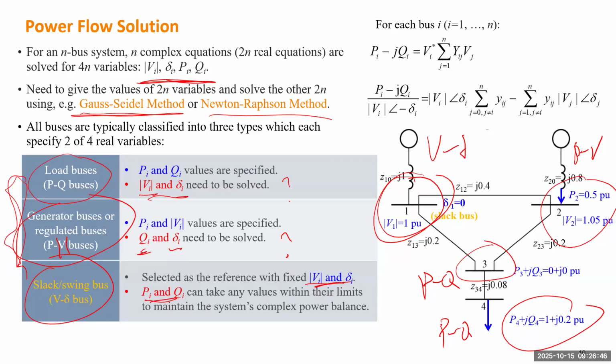Okay, so then this power flow problem can be solved. If you ask about any other types of buses, yes, you can definitely define any other types. If you have some new device which may be able to control, for instance, power and angle, or maybe the reactive power and angle. Reactive power can be controlled by a controller.